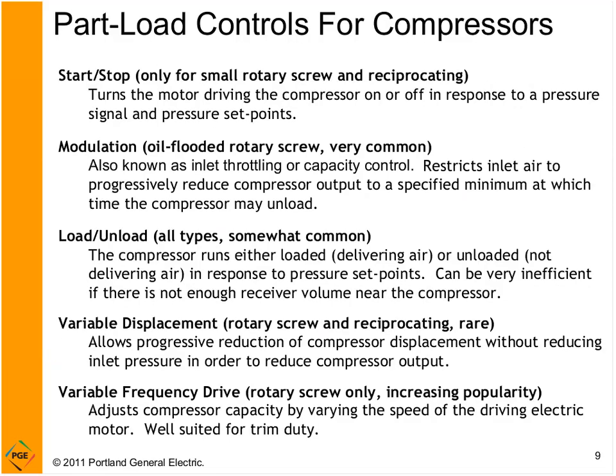Start, stop. Start, stop is really nothing more than an on-off switch. When pressure reaches a low set point, the compressor starts. When it builds pressure and hits a high pressure set point, it shuts off. It's kind of like your compressor you might have at home.